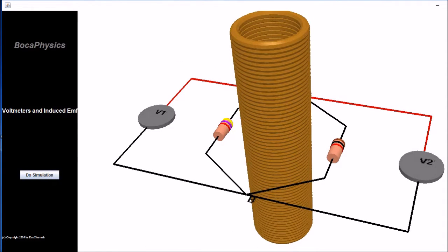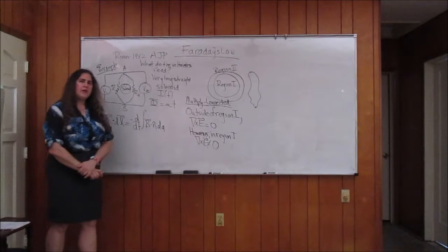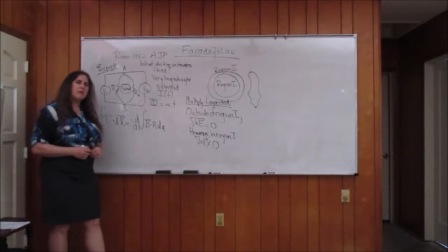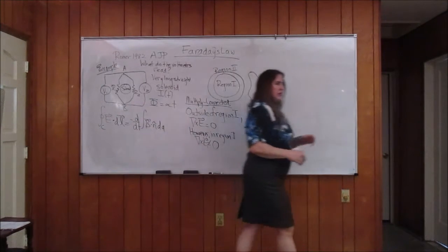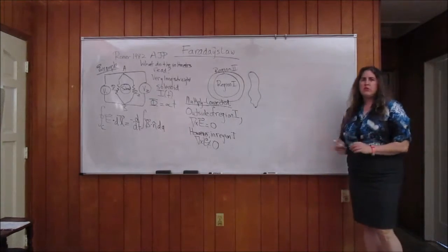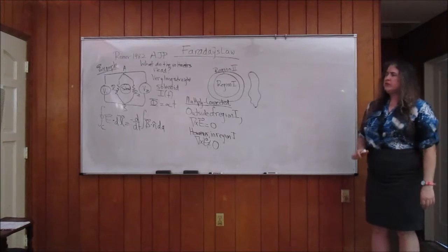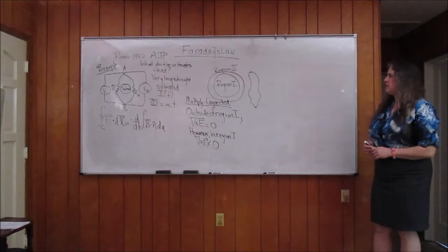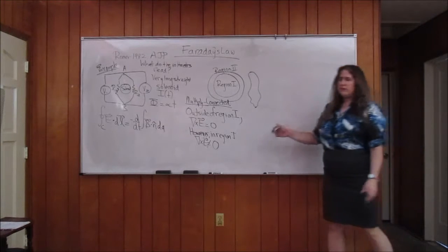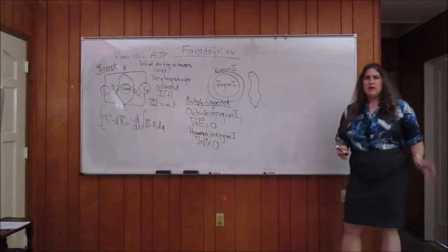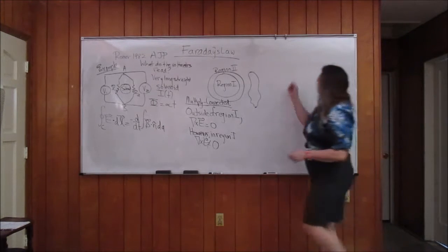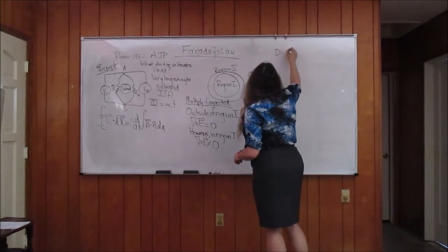Okay, back when we were first talking about EMF and Ohm's Law and those kinds of concepts, I first pointed out that, generally speaking, the topology does matter. We were concerned with surface charges. Now, there are certainly surface charges on this circuit as well, but it's not going to figure into the analysis. So we really are just looking at Faraday's Law and the effect of having a system with a multiply connected region. Before we analyze this particular problem, I'm going to look at a simpler DC circuit, just for reference.